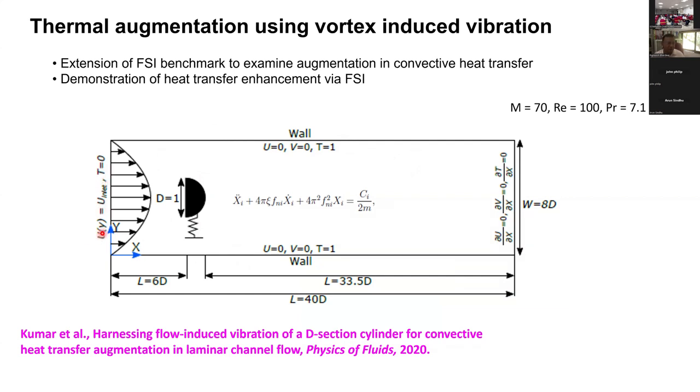As you see, our inlet velocity is non-dimensional 1, and the temperature 0 means ambient, and the walls are heated. The non-dimensional temperature is 1. We actually solve the spring-mass system equations, as you can see, in non-dimensional form here, and the Reynolds number is around 100, a very low Reynolds number, but it still gives a good idea of the mechanism of the heat transfer.